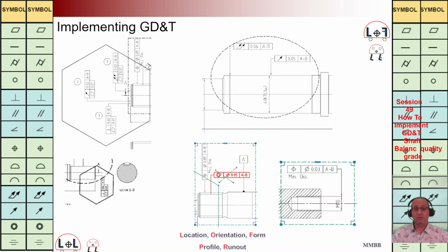Today I'm going to continue to talk about the needed GD&T for shaft. Let me recap the needed GD&T for shaft as we discussed last session. As we can see here at top left, for this end surface we need to use one of these three: flatness, let's say run out, or total run out, or perpendicularity.